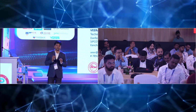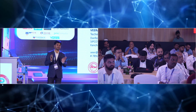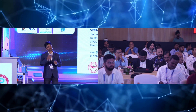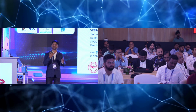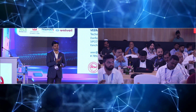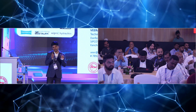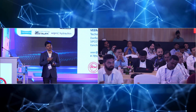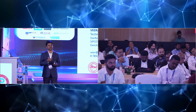And one of the headaches, even today, is cavitation. You can imagine 60 bar coming down to 3 bar in microseconds, below the vapor pressure, and then it damages the cylinder bushing. We have a special bushing arrangement to control that, and we replace only the bushing if it is damaged. And we have intelligent grooves which help us reduce the transition from HP to LP and from LP to the high pressure side.